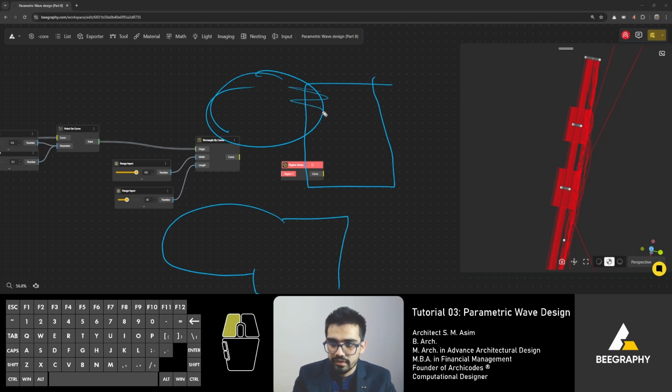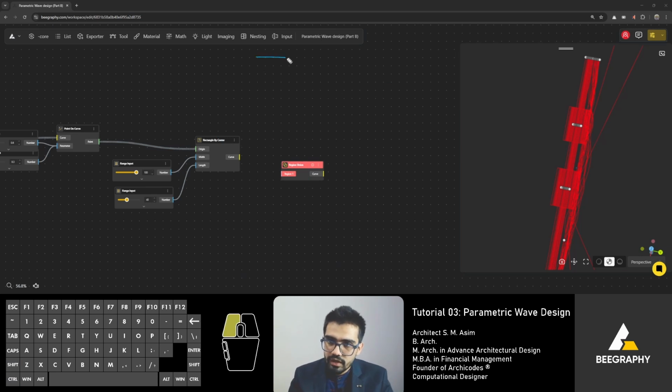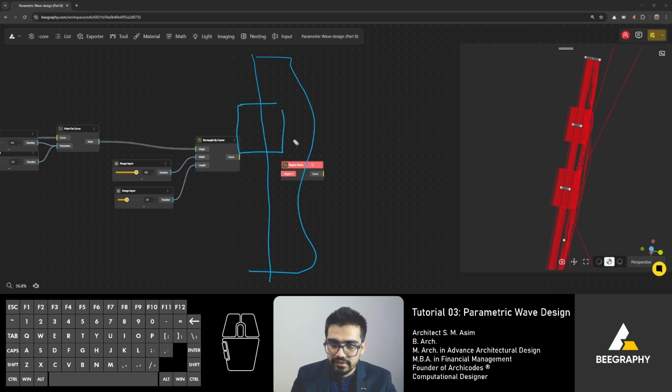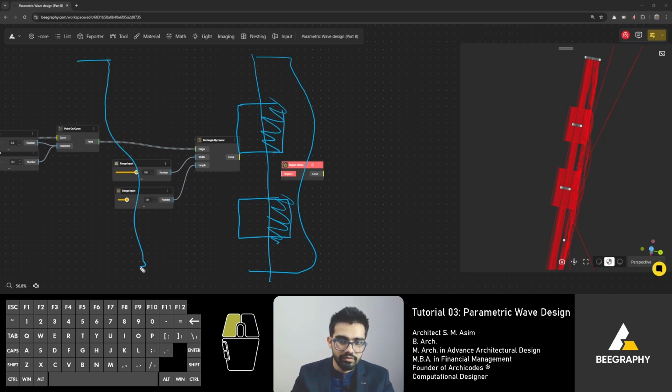It has eliminated this part. That's exactly what we want over here. We've got our wavy panels, right? And then we are adding in these rectangles. And if I do region union, all of this will get eliminated. And at the end, we will get the wave and the protrusions only. And that's the desired outcome.